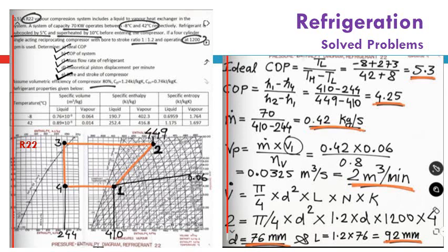There is a certain ratio given in this problem between the bore and stroke, equal to 1 to 1.2, so we can replace the stroke with 1.2 the diameter, and using the 1200 RPM and 4 cylinders, the equation will just have one unknown to be solved, which is the diameter cube.